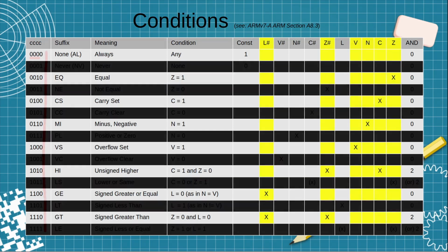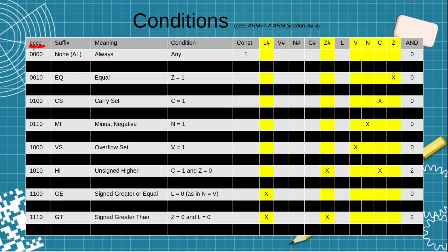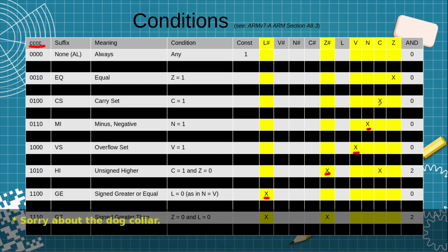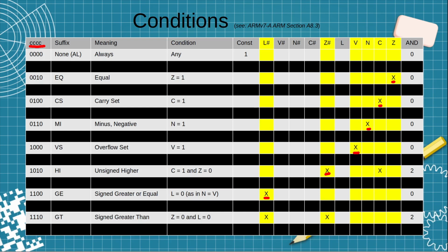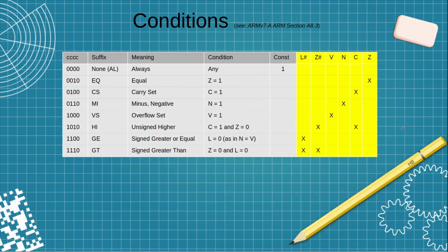Okay, so what flag signals does that leave us with? Basically anywhere where the least significant bit in the conditions flag column was 1, I blacked that row out. I highlighted any column where I still had a flag that I needed. And I got what looks like a bumblebee, so I condensed that down a little bit. And so these are the flags that I really need to carry off the board here. I don't need anything more than those 6. I had originally intended 10. So the flags that I need to carry off the ALU into the control circuitry are just those 6. Let me clean up the circuit verse model, and I'll come back when I have that done and show you what the result is.